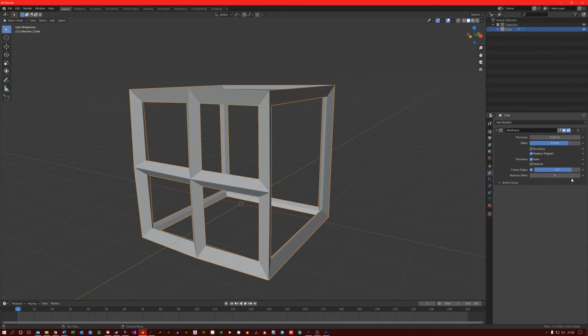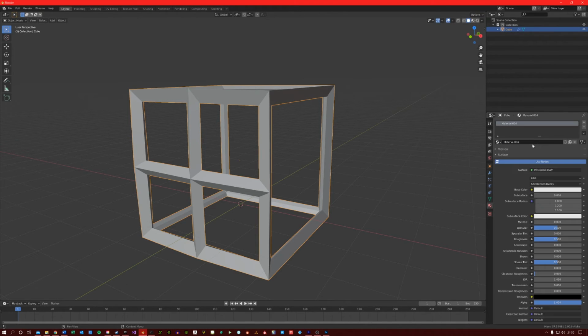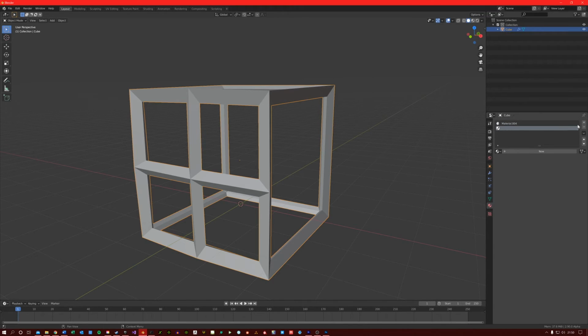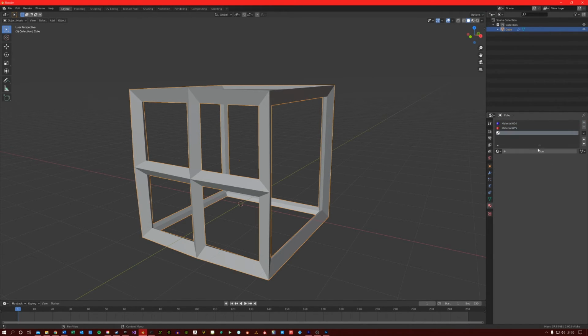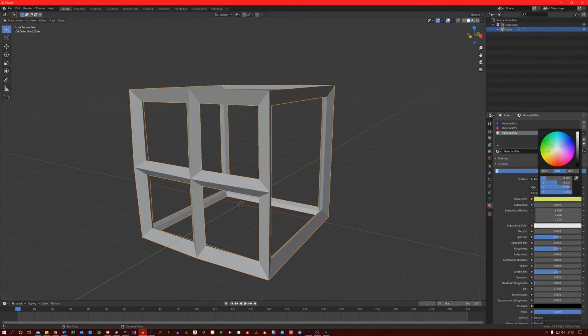And the material offset option here just reads whatever material is on the material index of the mesh. So for example, if I create 3 materials, blue, red, and yellow. So Blender will read this as an index. This is 0, this is 1, and this is 2.